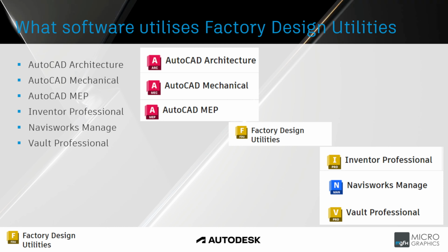When I talk about a little bit of 3D, take AutoCAD Architecture. If you've never heard of it, it's an AutoCAD-based architectural piece of software which works very much like Revit does. You set up your walls, maybe a 270mm wall with a 50mm cavity, and as you draw and connect the walls to each other, it will join them as it would in real life. If I'm planning out a factory layout, I would like to also see the walls and where the doors and windows are.